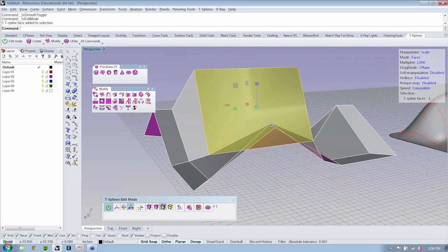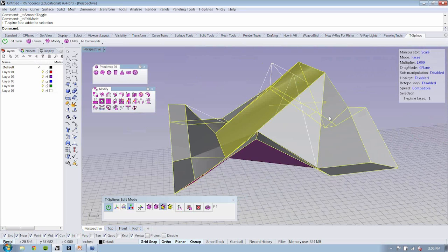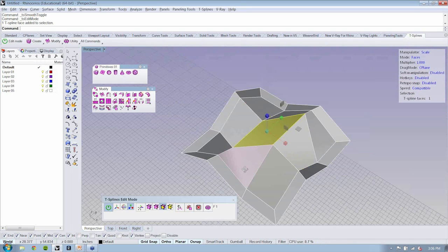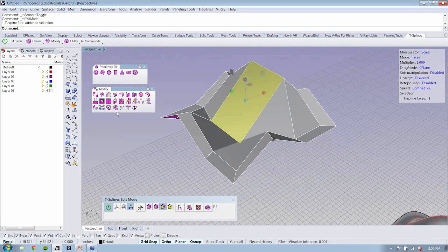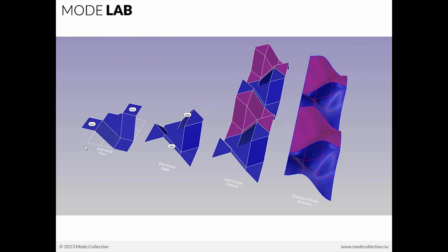Right. If I want to make it undercut or expose it a little bit more. Right. So combining the translate, the scale, and the rotate allows you to very quickly start to manipulate the character of the geometry that you're working with. So again, from that simple primitive, moving the faces up, you can start to develop a simple component or a simple piece of T-spline geometry, which, if you were to copy it over or mirror it over, can begin to act as a continuous T-spline surface.